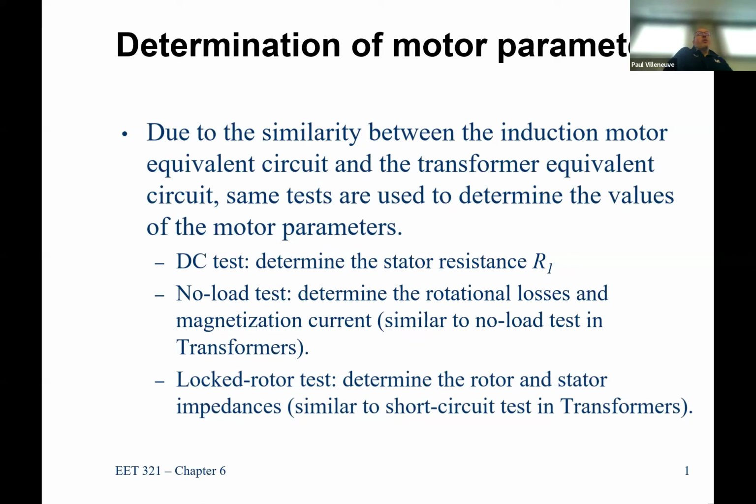The reason why you don't want to do just a heavy load is because it's difficult to replicate the slip, right? So if it's rotating, even if it's rotating slowly, you're not going to get a slip of 1. So that R2 divided by S you get in the secondary circuit, all bets are off, right? You can't get there. So if you know that it's not moving, R2 over S becomes R2 over 1, and then you know what the rotor resistance is.